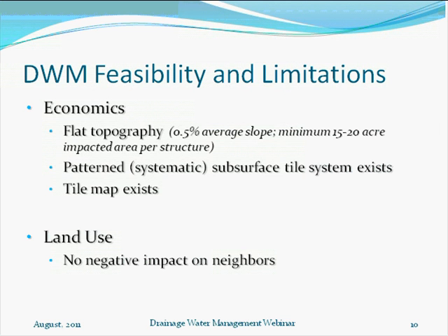The other thing to consider is, what about additional conservation practices? What if, tied into that subsurface tile system, we also have, say, the outlet to underground outlet for a terrace? Probably want to take a pretty good look at it and decide if doing drainage water management is going to make our terrace fail. So we're going to have to think about that too. It's going to affect the limitations on drainage water management in certain fields.